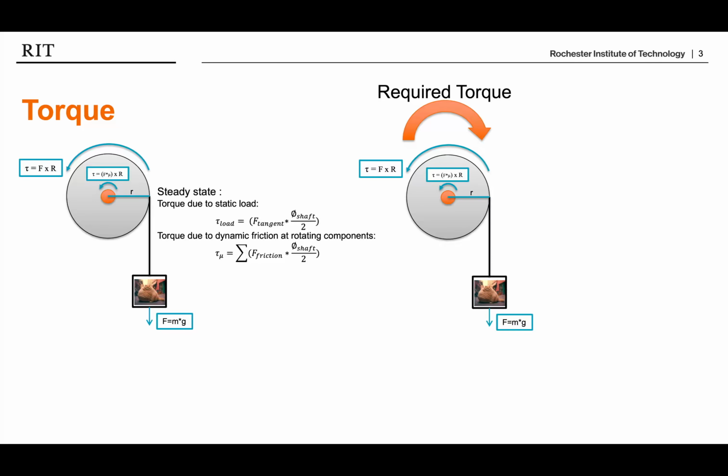Now I also have a real system, so we can also make the assumption that there's probably some sort of friction in our system, and these torques add to that system. So for example, maybe I have some frictional coefficient where the cable is riding against the drum.